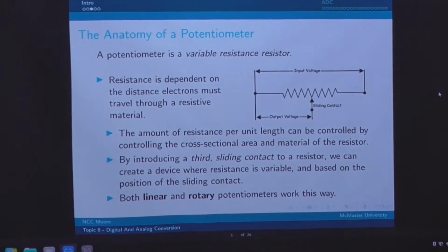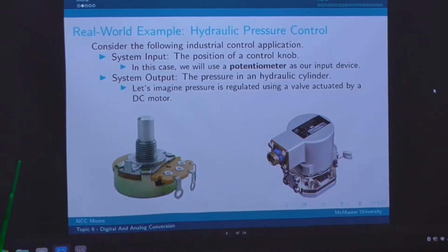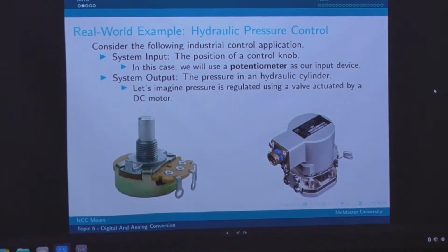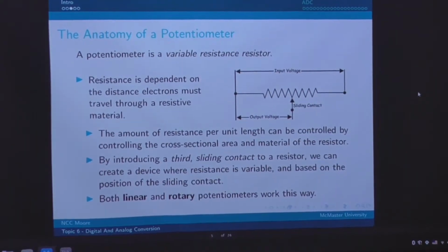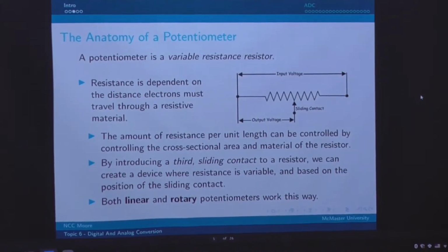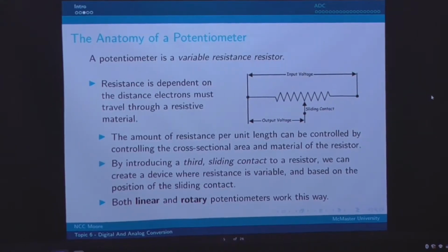The example on the previous slide is a rotary potentiometer. The ball and beam example that I gave you is an example of a linear potentiometer. Good. So these things output in analog, right? You'll get a voltage somewhere between 0 and +5 if you apply +5 to it, right?